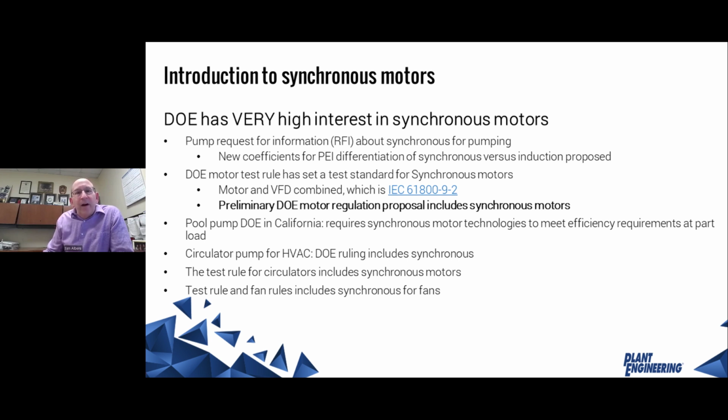And there are a number of DOE rules for end equipment, such as pools, circulator pumps, and some smaller ones like furnace fans for houses and a number of other items, where the DOE has effectively ended up requiring a synchronous motor to get to the system efficiencies. Just recognize that synchronous is definitely a thing, and it's going to continue to be a significant portion of power drive systems implemented as we move into the future.